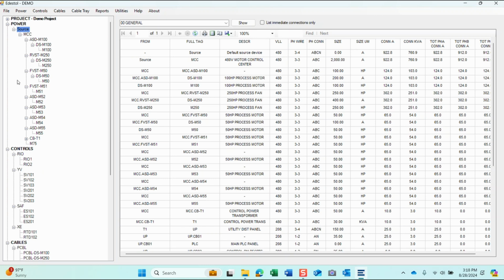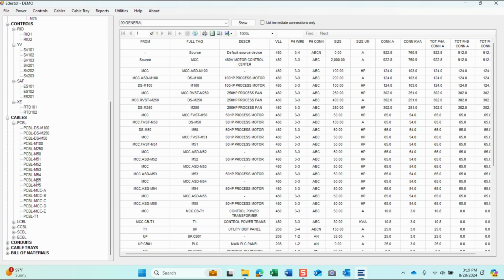It turns out that a power system is represented very well by a tree view, and the power flows up and it calculates based on the National Electrical Code rules on input ratings of drives and largest motors and 125% of your continuous loads, and all of those things that are required are done, and you can look at your power system in a lot of different ways. If you assigned lengths to your conduits and your cables, then you can do bill of material reports at the end.